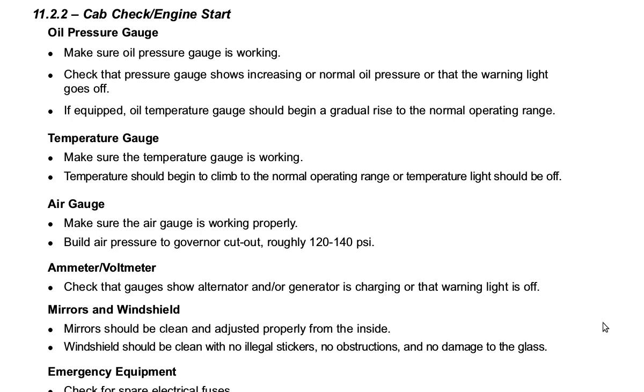Cab check, engine start. Oil pressure gauge. Make sure the oil pressure gauge is working. Check that the pressure gauge shows increasing or normal oil pressure, or that the warning light goes off. If equipped, the oil temperature gauge should begin a gradual rise to the normal operating range.